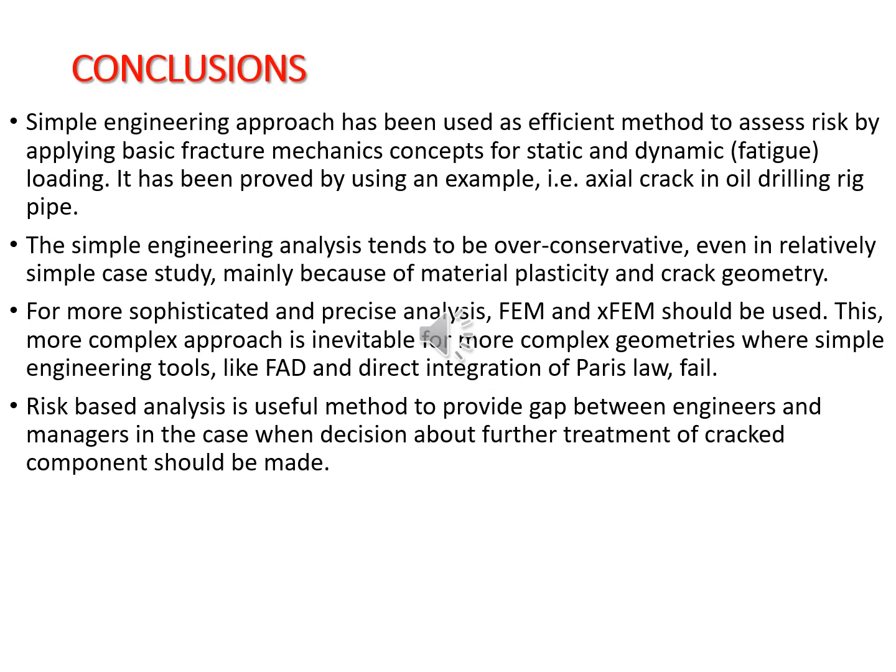We have seen that a simple engineering approach has been used, and it turned out to be a very efficient method to assess risk. We have applied just basic fracture mechanics concepts. More generally, it was applied for static and fatigue loading. Here presented only fatigue. The analytical tools we used, like integrating Paris law, turned out to be over-conservative, even in this simple case study. So for more sophisticated and precise analysis, we really need the finite element method.